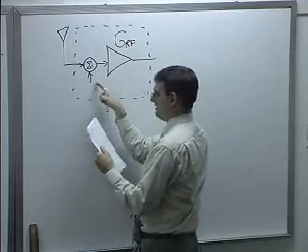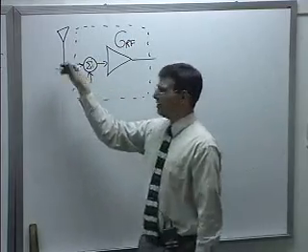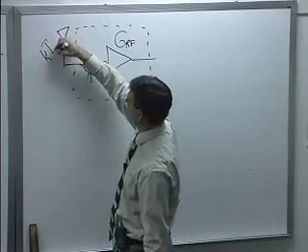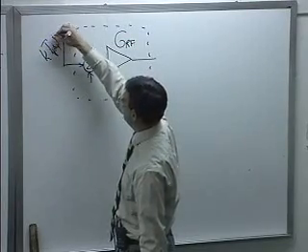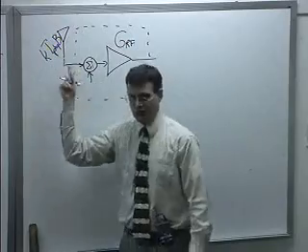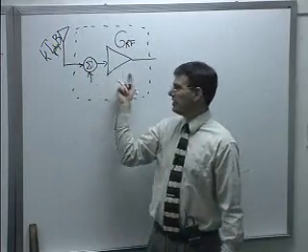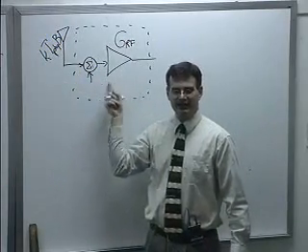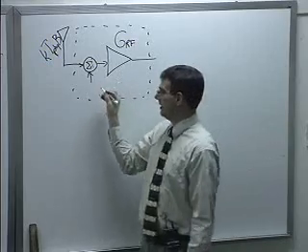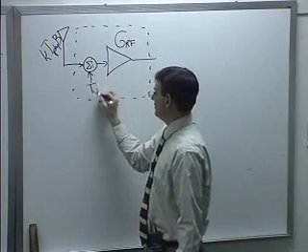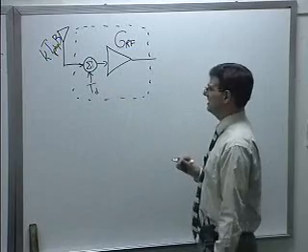And the amount of noise that gets added in here, we like this model of k times physical temperature times bandwidth so much, and it works so well for describing roughly what is white noise that gets added in as a device temperature, that we usually just use a temperature to describe the device, T sub D.